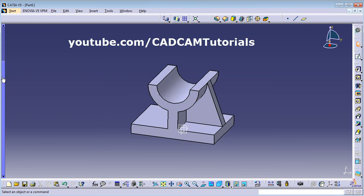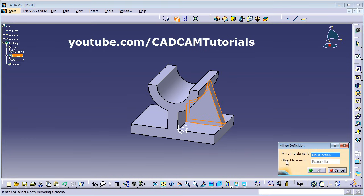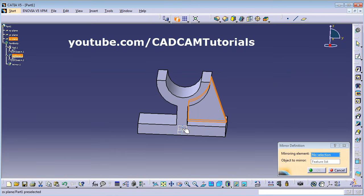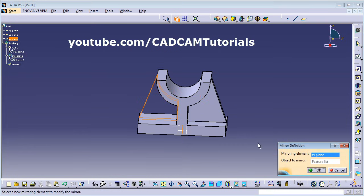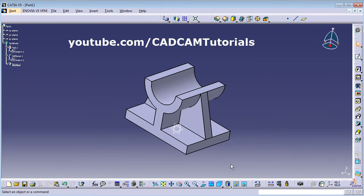So what we will do, we will go here, click plus before the part body, then click on the stiffener feature, then click on mirror, then mirroring element, define the mirror plane. The mirror plane will be vertical at the center, in the middle of both the objects. So we will take this mirror and click OK. In this way this object is ready.